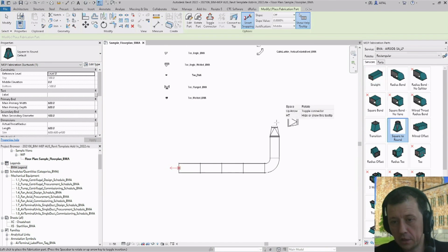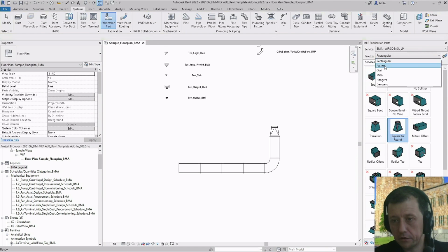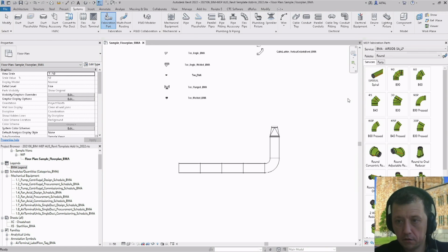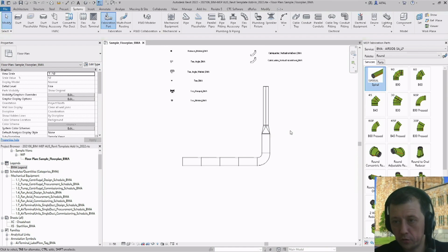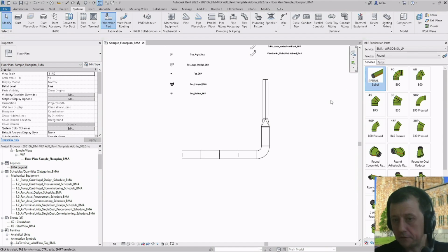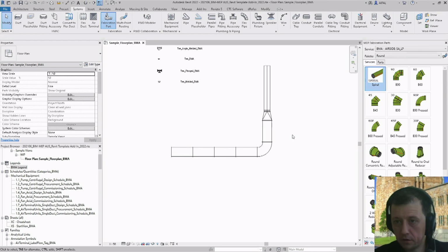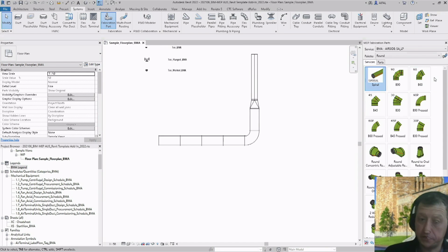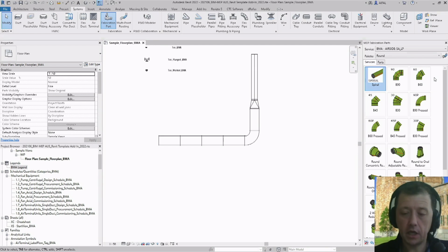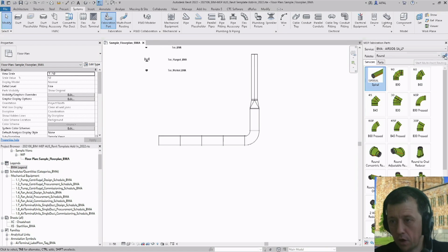And now I want to go on here with some round ductwork, and I just change this palette to round and add that piece of duct. There's one way you can do it, that you just drag and drop the single pieces, and that is how it worked in the earlier versions of Revit. In the meantime, we now have the option to also use multi-point routing, which is pretty similar to how Revit works. So let me go up here. You have that start multi-point routing option.